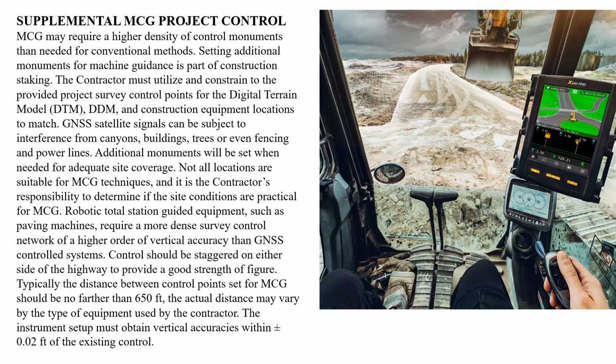So MCG may require a higher density of control monuments than needed for conventional methods. Setting additional monuments for machine guidance is part of construction staking. The constructor must utilize and constrain to the provided project survey control points for the digital terrain model.